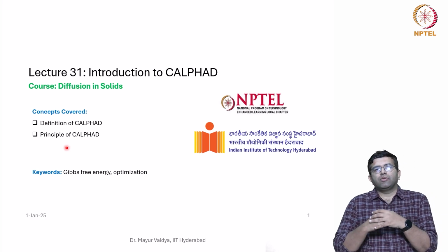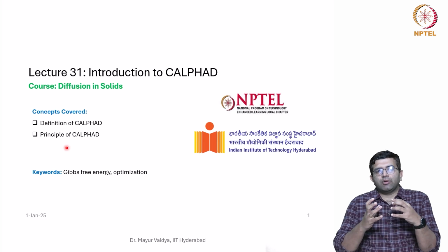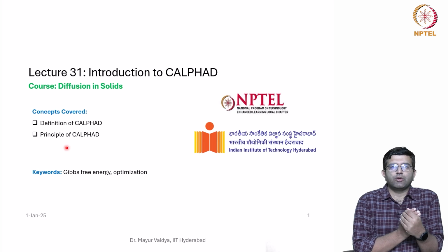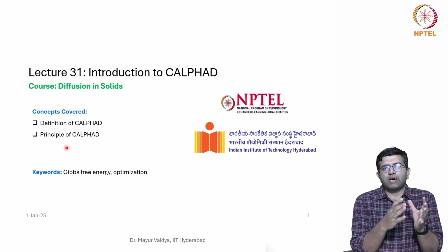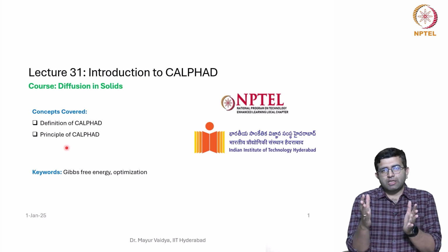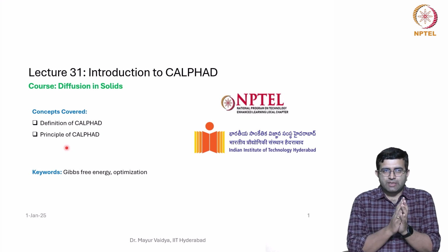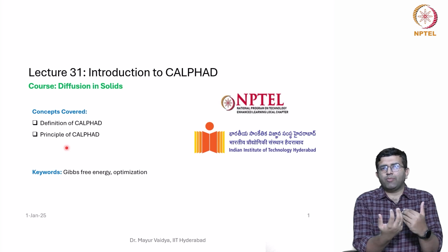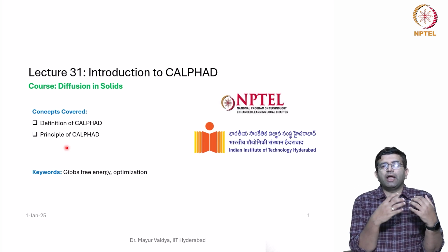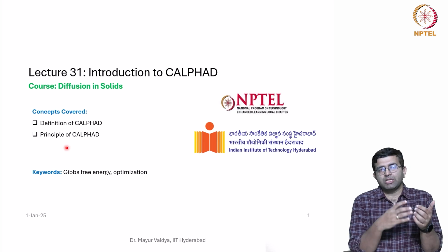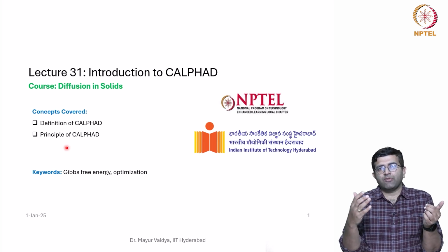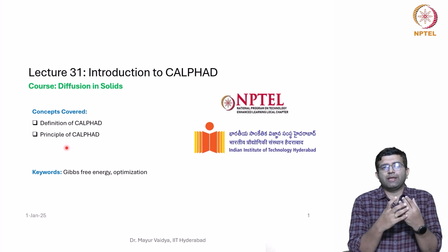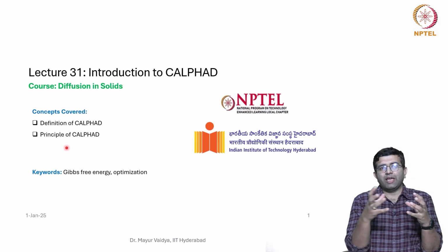Now, one of the things is that when you talk about diffusion-controlled processes, we know that the diffusion rates in solids are typically lower compared to liquids or gases. And given the nature of the many complex phases that can form, and the many material combinations, the phases are a function of temperature, compositions, and so on. So, a lot of the time it is not possible to do everything experimentally.